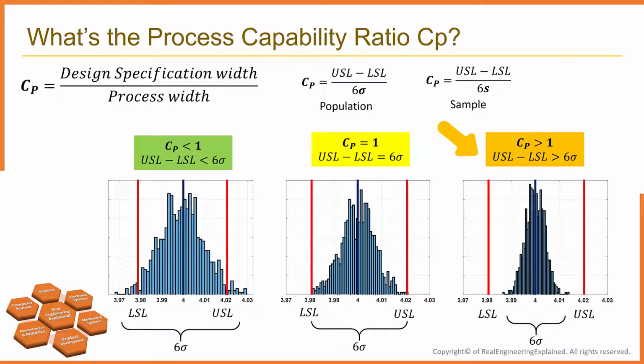We have a small variation for the dimension and are completely within the specification limits defined by the customer. Please note that the assumption here is that the mean is well centered and is not shifted. With this assumption, which one is the more capable process? Of course, the higher value for CP. We will have less variation and less failure rate.